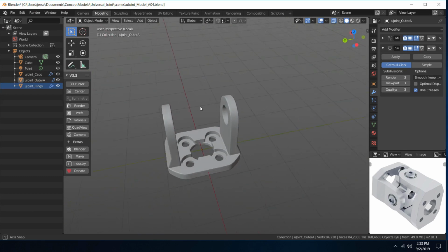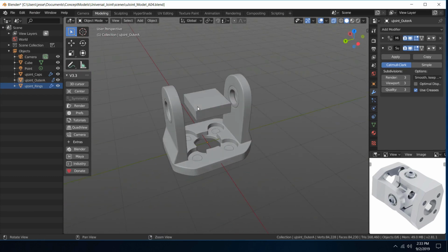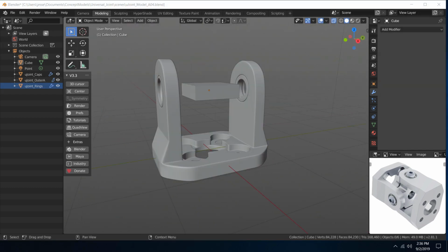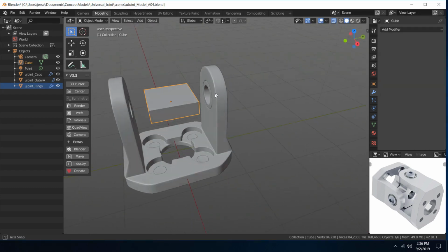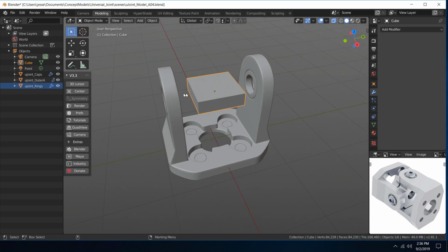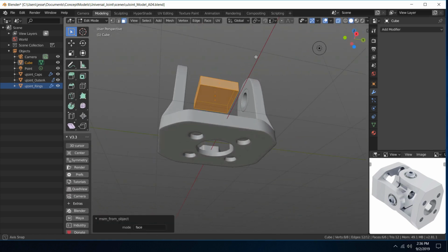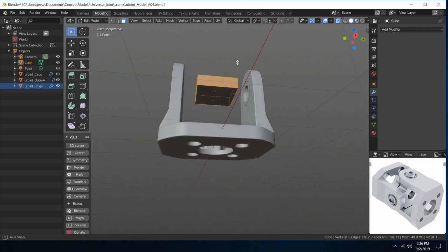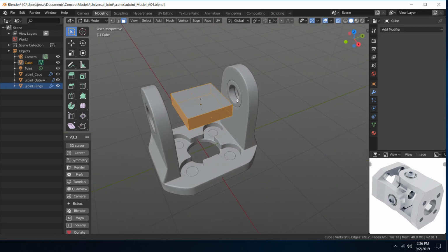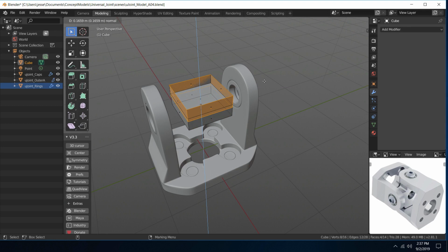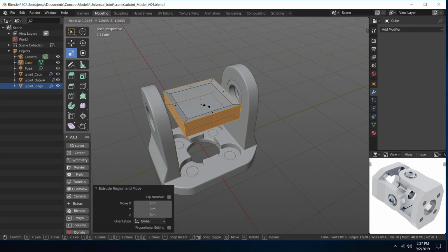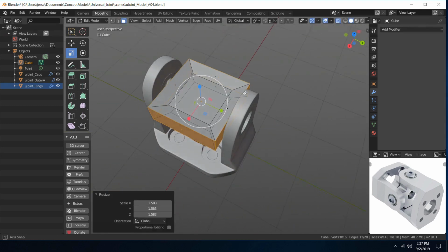Alright, so that's a little bit better, but we can finesse that some more later. So going back to this guy, we want those 4 extrusions to make our plus sign. Just going to deselect those middle ones. And now we don't want to just do a normal extrude, which is extrude faces, hitting escape, because we get an extrusion that's all one unit.